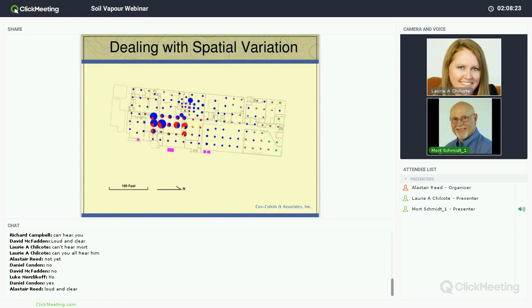This is a picture of a building where we conducted our first gas survey using the vapor pin about 5 years ago. We had just 2 guys and a hammer drill, installing 30 points a night, letting them equilibrate for a couple of hours, sampling, pulling a vapor pin, and plugging the hole. Over the course of a week, we sampled 140 plus points.